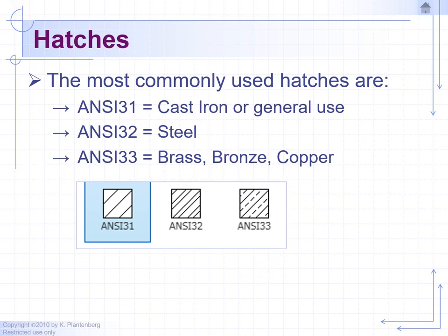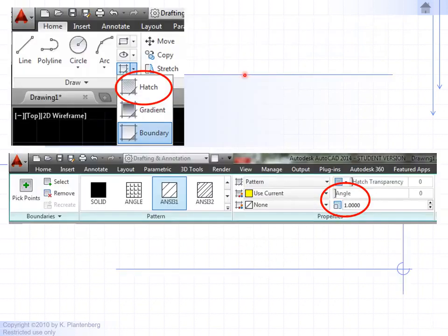Next slide. To access the hatching pattern command in AutoCAD, look below the ellipse. Here we have the hatching pattern command. So we have hatch. There's also gradient where you can mix colors and you can change the brightness of the colors, the mixture, the pattern of colors, which we don't really use in mechanical drafting, but it's great for visuals.